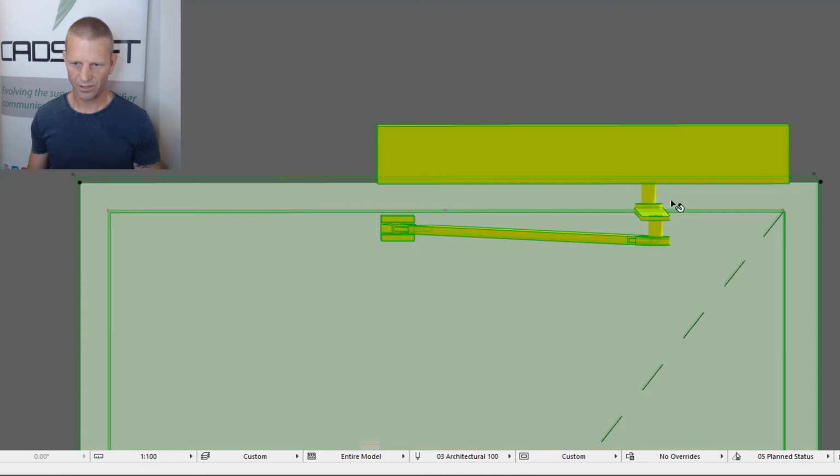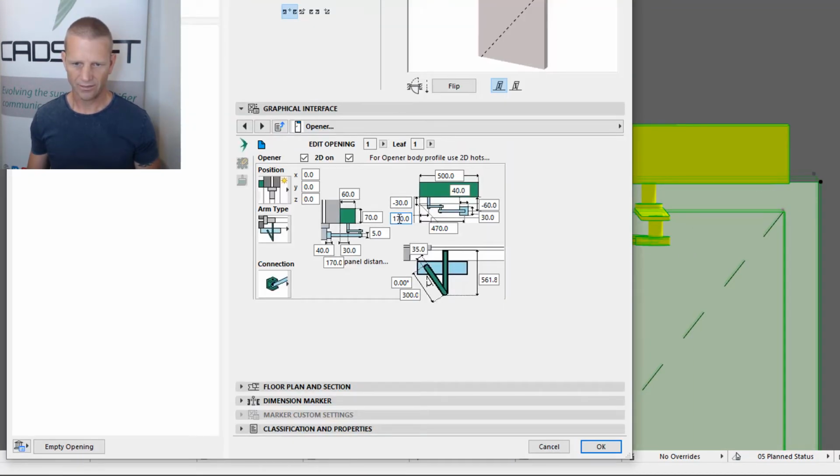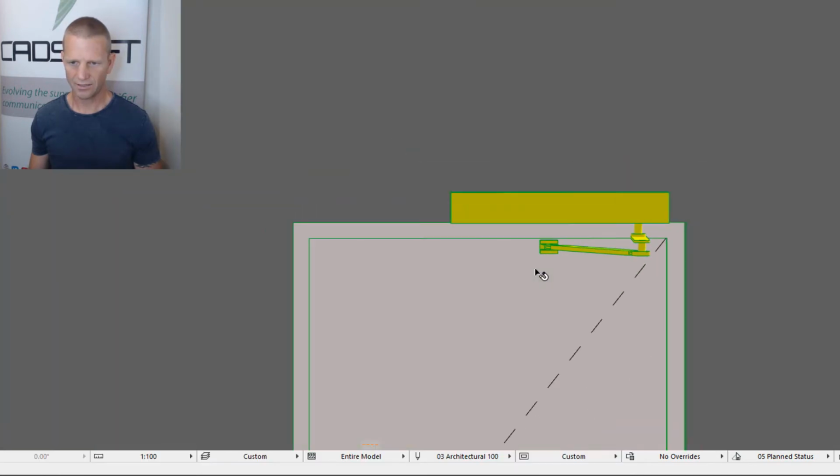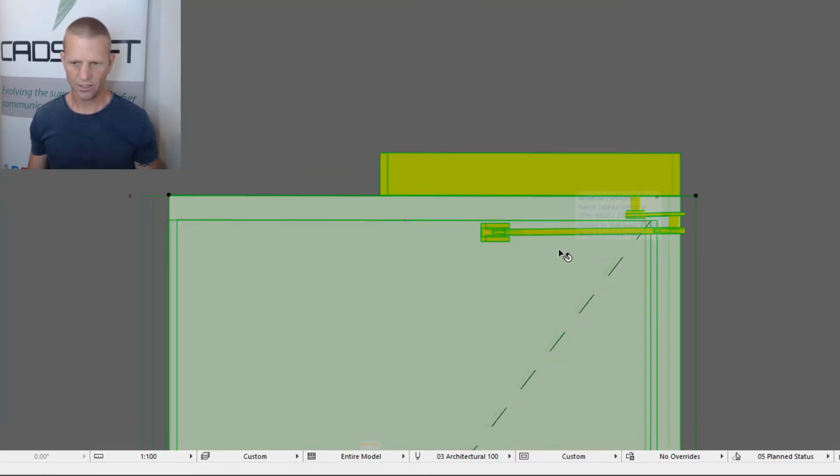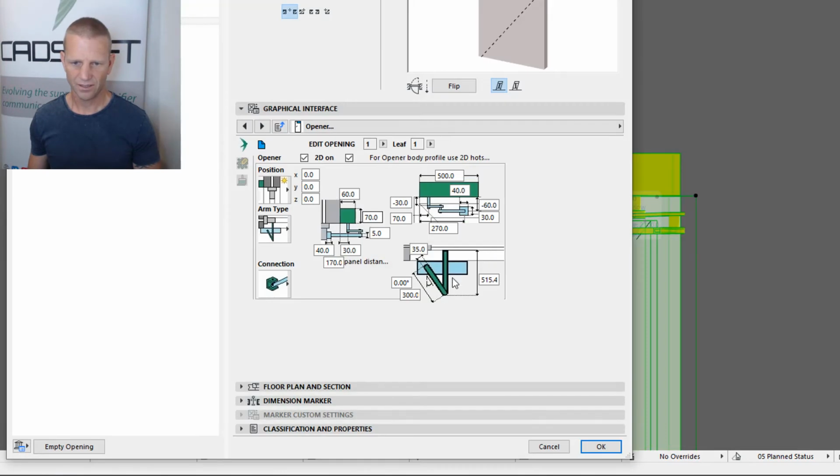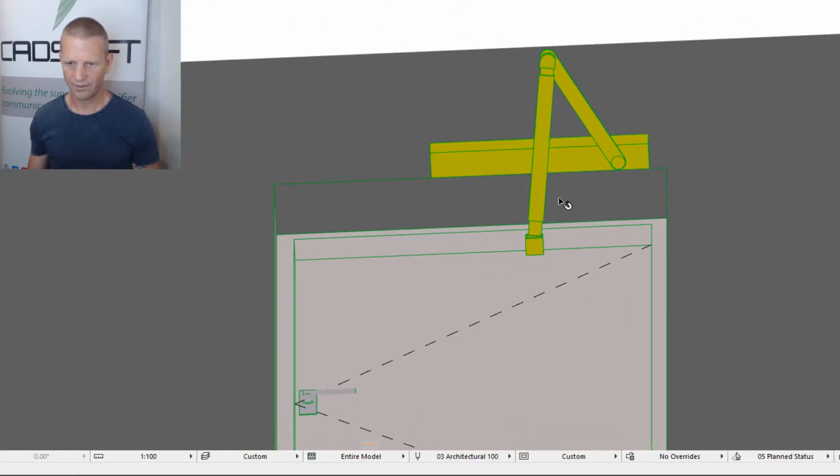And we'd probably shift the whole thing over to the side a little bit more as well. So this one's 70 to 70, and let's adjust the positioning of this point here as well. It doesn't need to be so far away. Okay, so that's a little bit more typical. Let's go back into the element. You see you can also adjust the angle of this element. So you may want that section to be straight and that section to be angled, so you need to adjust that a little bit. Let's just set this to 30, and now you can see that configuration.